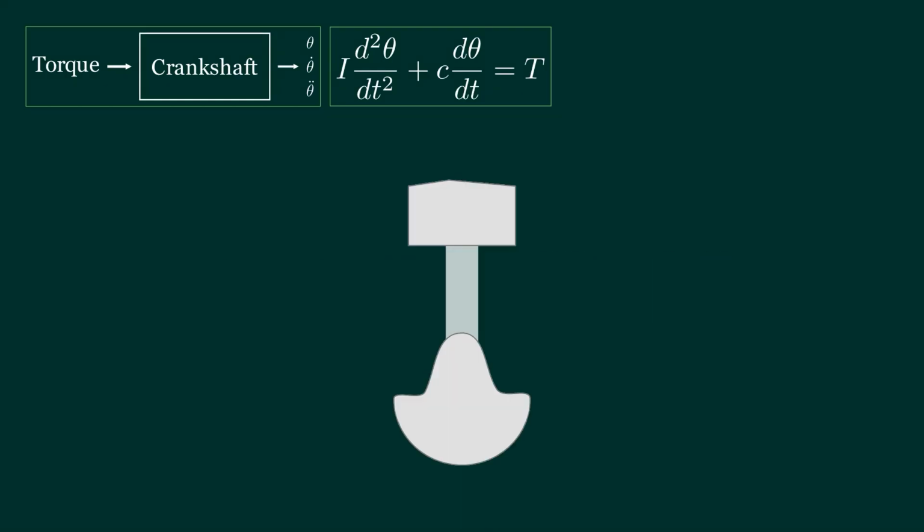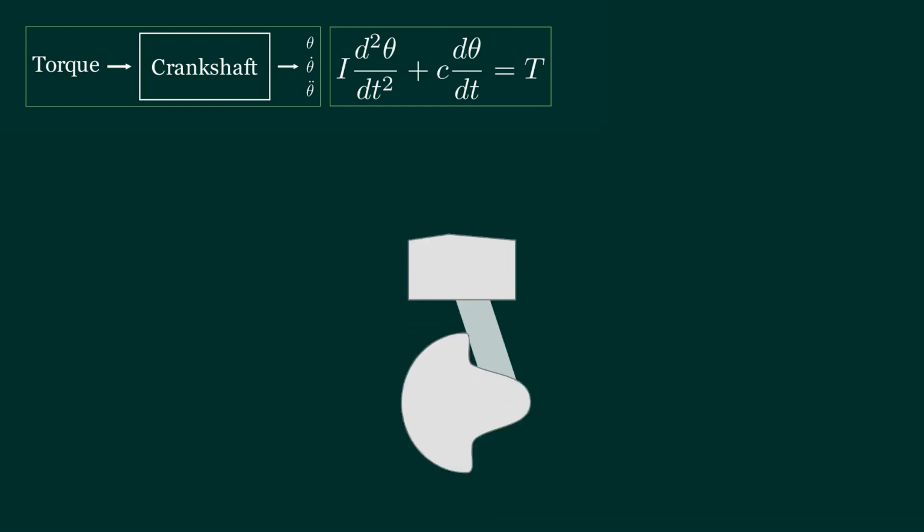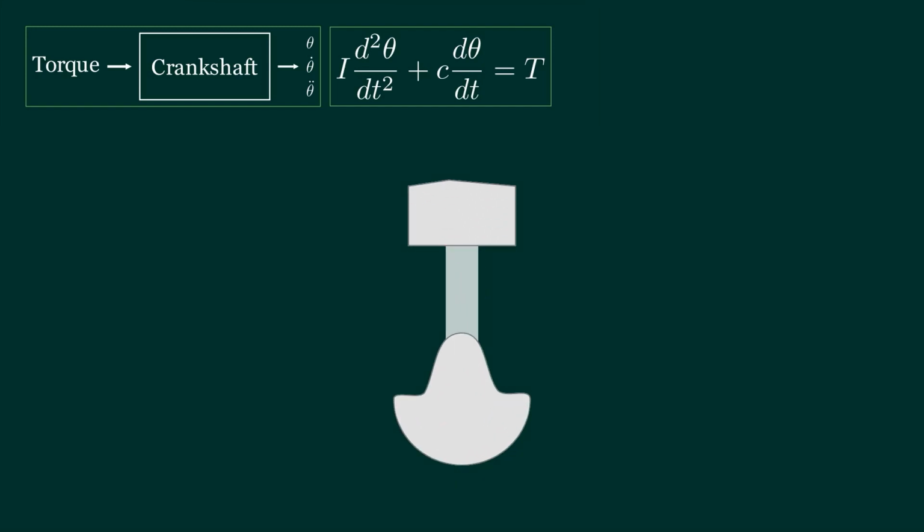Yet there is one more important thing to think about, which is the inside of the cylinders. We know that every time the crankshaft rotates once, the piston moves in the cylinder twice. So if we multiply 333 by 2, we would be able to sample one piston stroke. But with that frequency, at 20,000 RPM, while the piston is moving like that, we will see a piston like that.